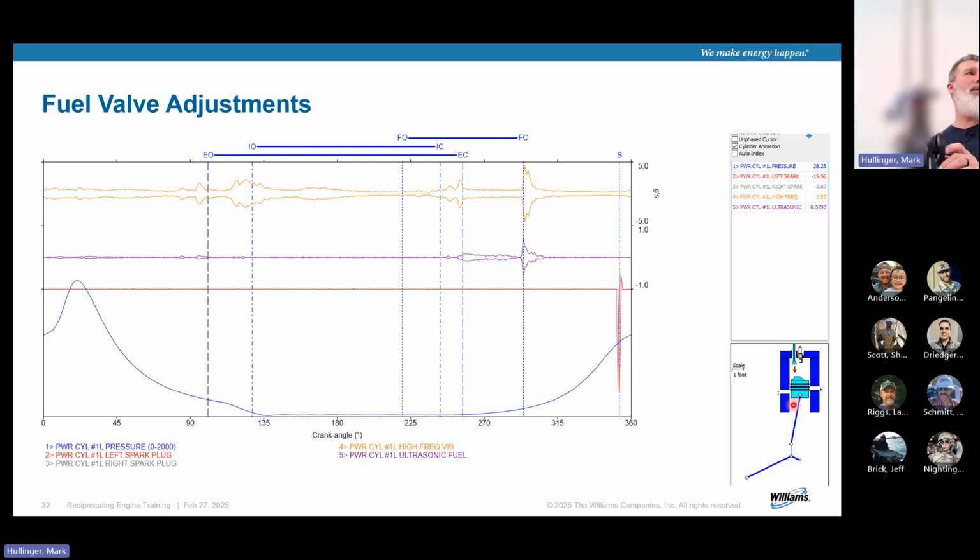Yeah. So the comment was made, 2-stroke, you get a power kick every 2 strokes. 4-stroke is a power kick every 4 strokes. A 4-stroke just breathes better. So it just does one more breath and then it fires. And so the mixing happens a little bit better. So they're generally cleaner. And 2-strokes, you just throw fuel at it and it just combusts when it can, essentially. Maybe that's a loose way of saying it, but that's how I understand it. At least that's what you do with the motorcycle. You just go, right?